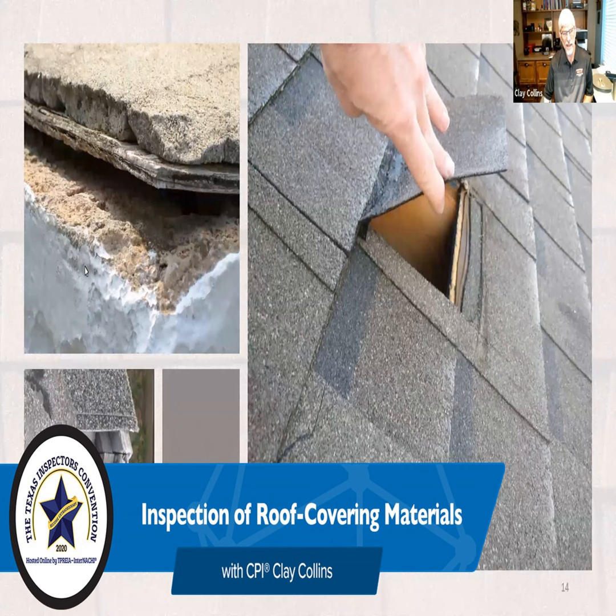Luckily, I was able to see that there was something wrong with that shingle before I stepped on it. That would have been a bad thing. But there's nothing stopping wind from lifting that up. We'll talk about adhesion in a little while. But you can see it'd be very easy for wind to blow that up, water to go down, and that shingle would set back down, and you might never be able to tell.